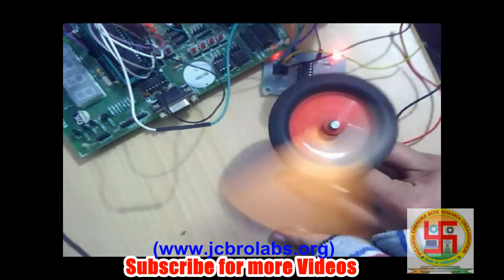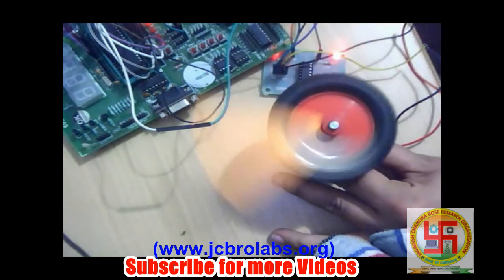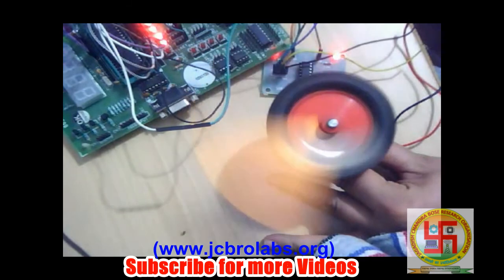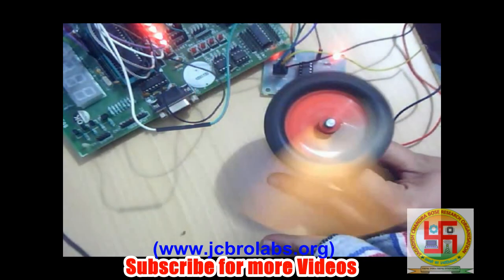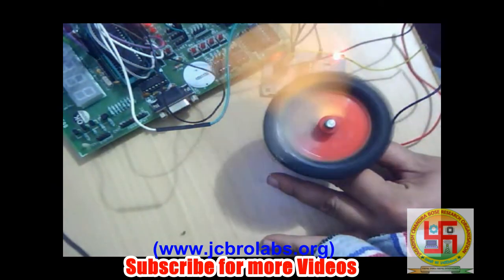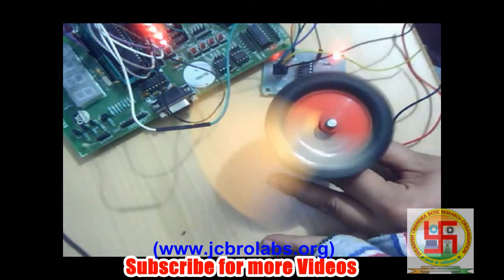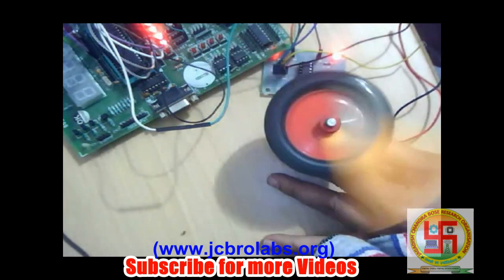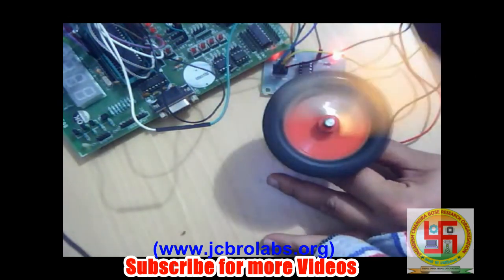Now the problem is, if we connect these pins of the DC motor directly to the microcontroller, the microcontroller won't be able to run the DC motor because it takes a lot of current. That is why we use this driver IC here. So I hope you learned how to interface a DC motor to the microcontroller, and this is very simple. Try it by hand, and if you have some doubts, you can comment below this video.